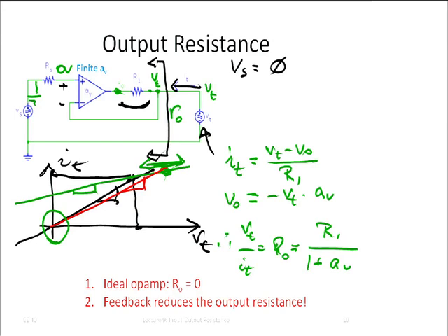Yeah, of course, if it's a voltage source, a perfect voltage source has 0 output resistance. So if I want to make a source with really low output resistance, either I can somehow miraculously make a source that already has 0 output resistance, turns out that's really hard, that's basically not possible. Or alternatively, I can make one that has as low an output resistance as I can, and then I use feedback with high gain, and then the output resistance is divided down.